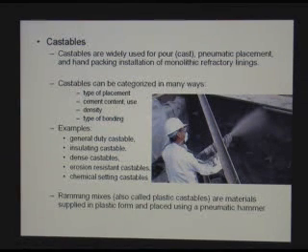And here's an example of how they are called in catalogs and vendor data. There is a special type of castable which is called a ceramic mix. It's also called plastic. These come in the final form like a brick, and you place them in the area you want to use them and pound them into place with a pneumatic hammer.